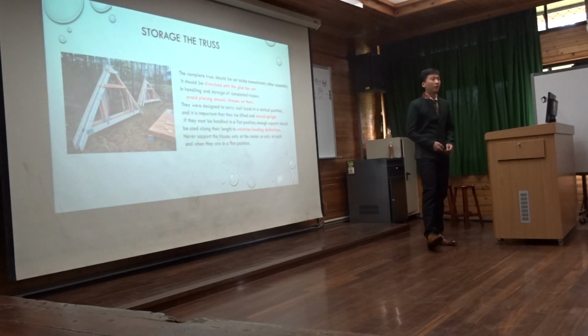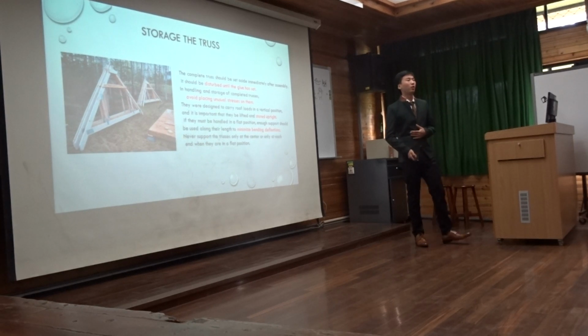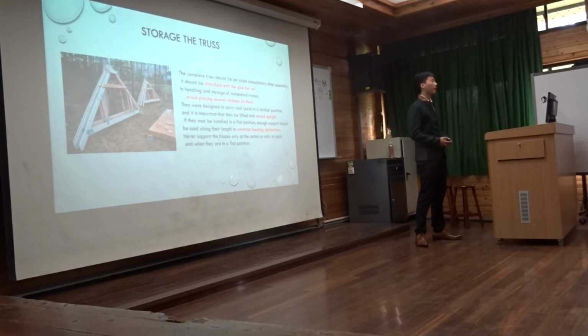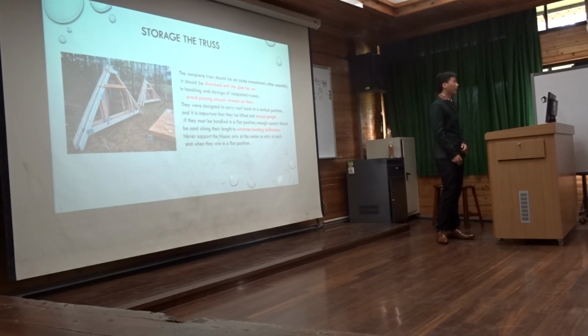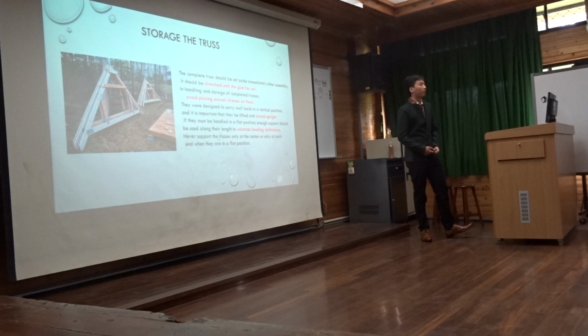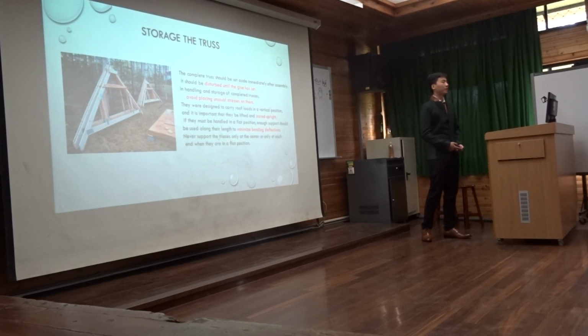After finishing a truss, we must know how to store it. The completed truss should be set aside immediately after assembly. It should not be disturbed until the glue has set. In handling and storage of completed trusses, avoid facing unusual stresses on them.